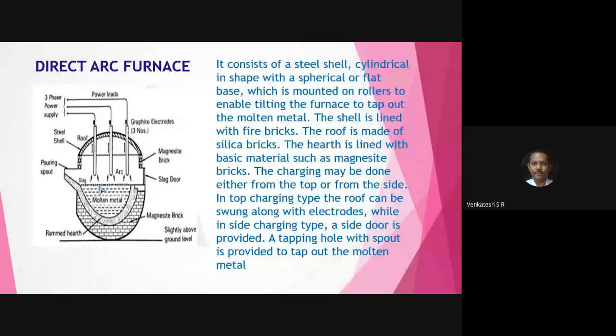The operator understands that the metal is ready for pouring, and then he rings the bell in the furnace department so that the molding section is ready to receive the liquid metal and pour it into the mold cavity. This is the principle of operation of direct arc furnace. All of you, please write down the direct arc furnace and also the rough diagram of direct arc furnace.